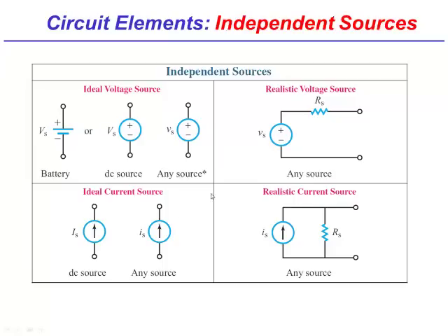But what you're saying here is that the voltage difference between this point and this point isn't always going to be Vs. It's really going to be Vs minus whatever the voltage drop is around the resistor. That's correct. Essentially, depending on what we connect it to, we're going to get a slightly different voltage here. The actual voltage is responsive to what we connect it to. That's right. It depends on how we use it. I got it. All right, this is going to be cool. This is interesting.